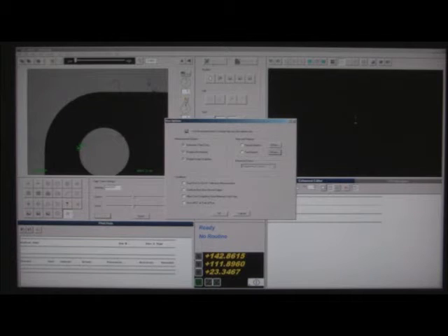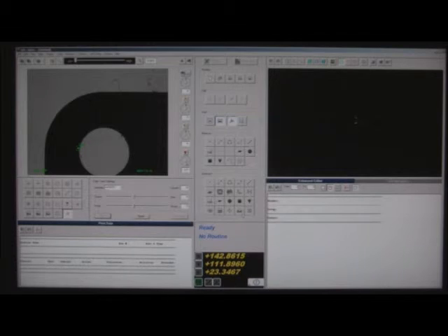Last thing, to force the machine coordinate system at the start of the run. We can set up datums, or set up a part or a fixture datum in the machine. When I start a run, I may not want those to be there, so I can say force the machine coordinates back in so that I have to start fresh again. So just some of the flexibilities you can have in the machine.